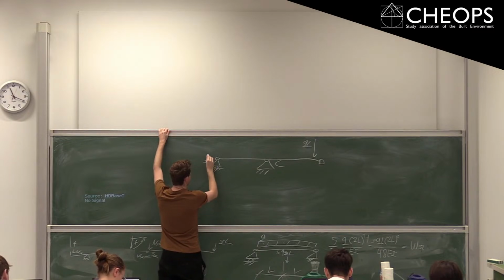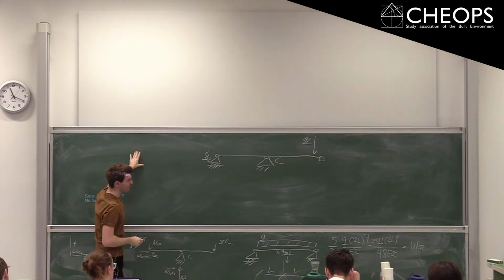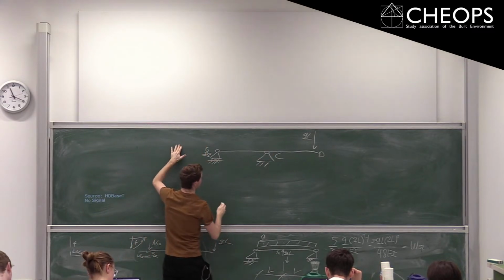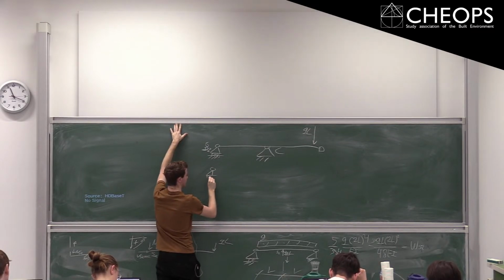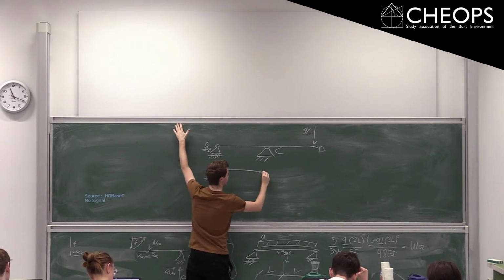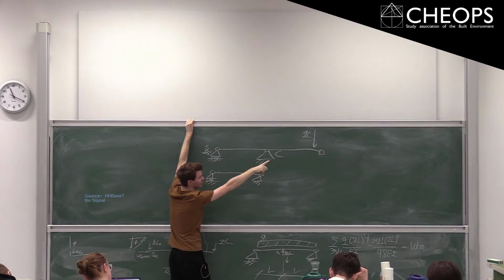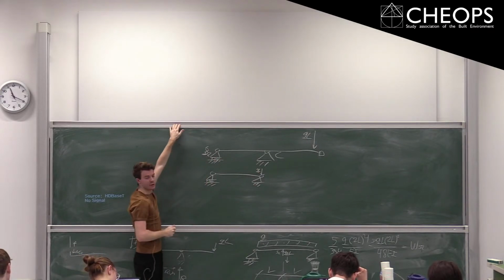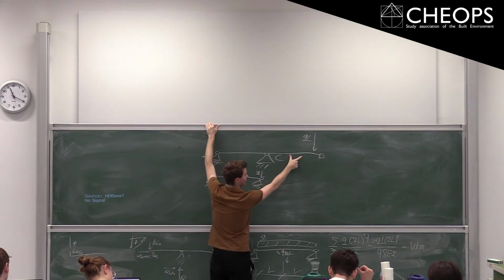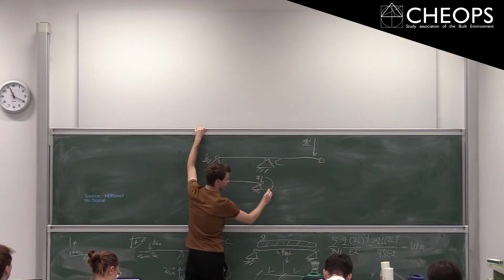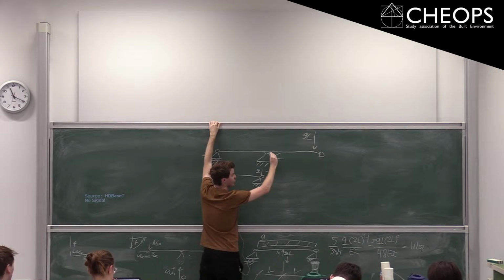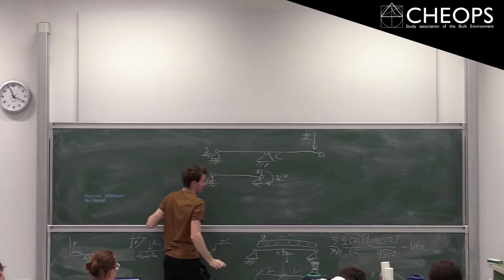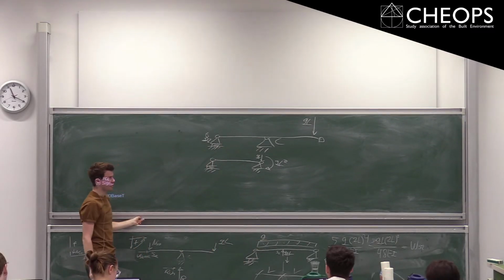With these kinds of things, you also have to work back to the case you know, right? So we know this part. So we're going to rewrite this diagram as an actual standard beam equation by simply moving those forces on the right to this part. The point load simply moves, but in reality it also has a moment contribution over here, right? So you get QL times the length over here, which is L. So you get QL squared. And this is the first step of our diagram.